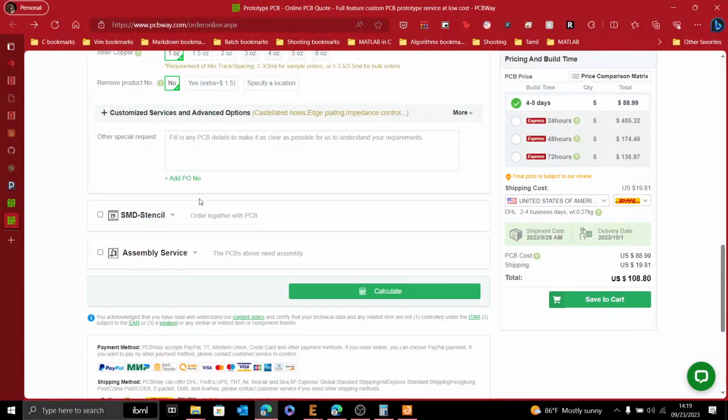provided you never hear back from them, like they will send you confirmations like order received, order reviewed, order manufactured, order shipped, stuff like that. You do have the potential of hearing back, hey, you forgot to include the drill file. I'll let you know how I heard that one. Your layers aren't matching up, or one of these Gerbers doesn't match. They have some kind of auto review process, and they'll come back to you like something's missing and you just need to correct it. But assuming everything is right, you would upload the zip, it would go through their process,